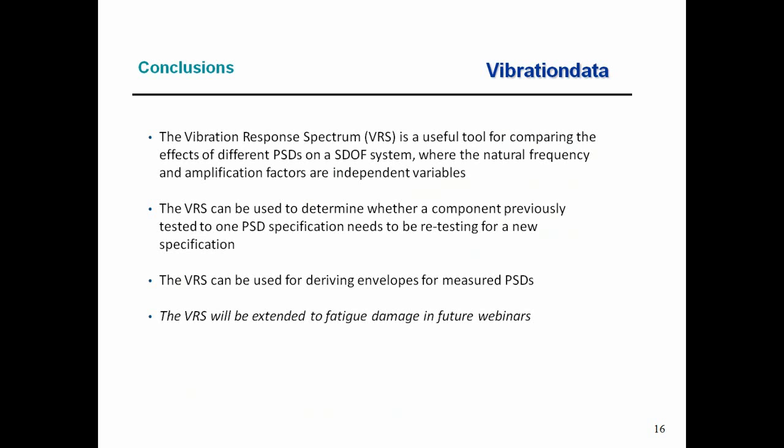But later on, we're going to be concerned about things like, well, what if that flight data had non-stationary time history? What if its histogram was non-Gaussian? What if the test duration and flight durations are some different numbers there? So what we're going to do in the future is look at something called a fatigue damage spectrum, and it's going to be based on rainflow fatigue. But in the meantime, let's just wrap up here.